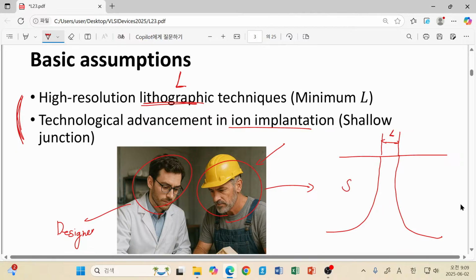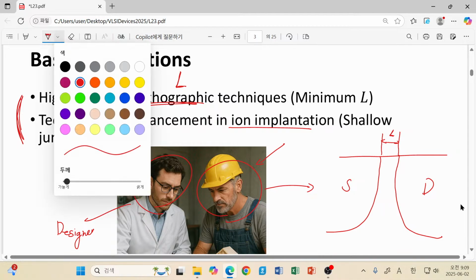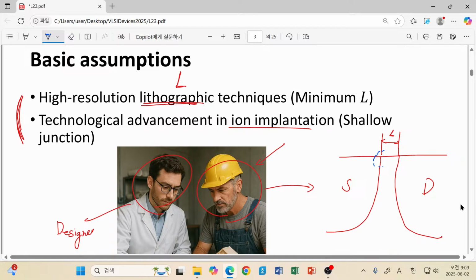Say that this is a source and drain. Then what will happen? In this case, it is sure that the part near here is completely controlled by our gate. However, there will be direct communication of charges between source and drain. So if our source and drain regions are too deep, then they are far from our gate terminal and not controlled by the gate. It means that an unexpected current conduction occurs.